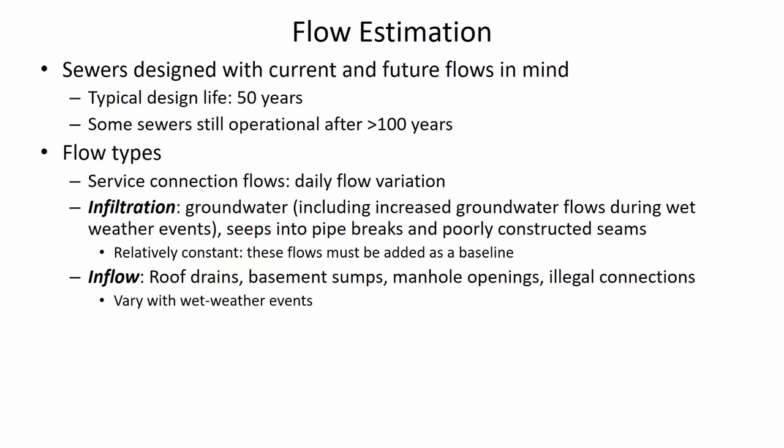Now here's a couple of important terms that you should be acquainted with. Infiltration is when groundwater is seeping into drainage pipes because the pipe is either broken due to lots of years of aging or differential soil sediment that can cause cracks in concrete pipes. And inflow can be related to illegal connections where people are maybe connecting a basement drain to a stormwater or sewer network that they shouldn't be connecting a basement drain. It can be where there are small ventilation holes in manholes that's allowing in wet weather flows.